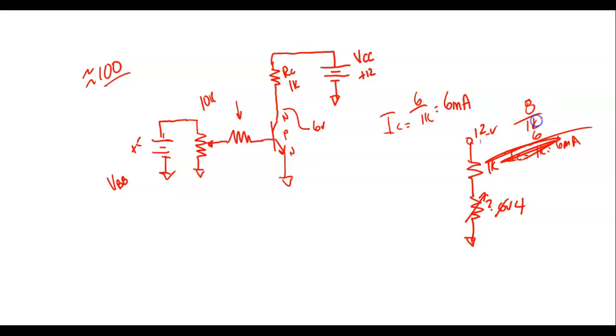So now this is going to be 1K, right? You understand? This is going to be 8 milliamps. So what would the resistance of the transistor be? Well, it's going to drop 4 volts at 8 milliamps. What you got to understand is the resistance of the transistor changes. It's a dynamic device, right? You understand? All I got to do is change base current. So what we're doing to control that resistor right there is we're controlling this with base current.